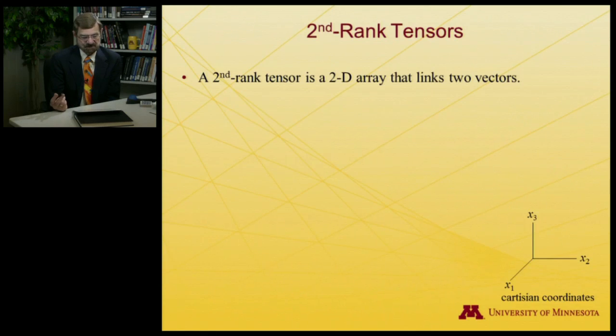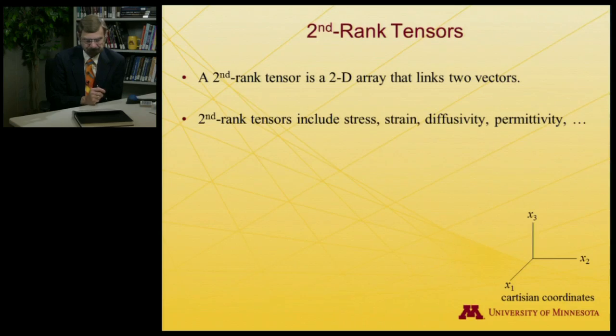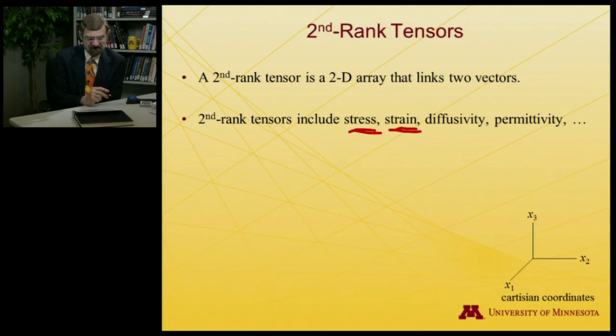Now we want to talk about tensors, which is where we dig into talking about our quantities, stress and strain, which are important topics in this class, and later on we'll expand this to strain rate. We're going to talk about these as second rank tensors, or often the second rank is dropped and you simply talk about tensors, but later on we're going to talk about fourth rank tensors. So we want to keep in the back of our mind that this is in fact a second rank tensor. And basically a tensor links two vectors. The vectors we're going to link are things like forces and areas.